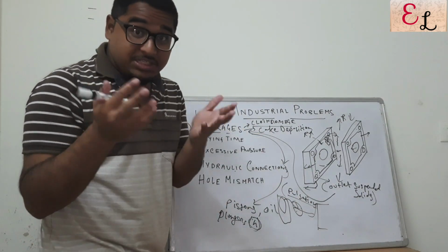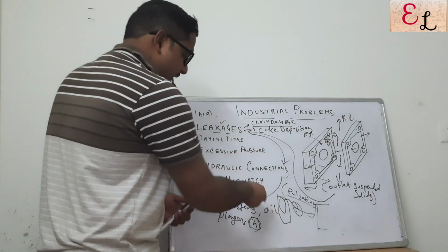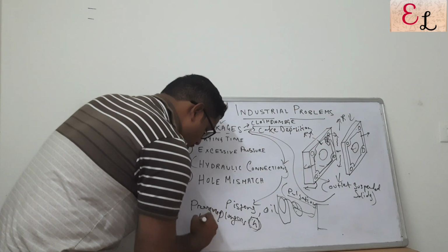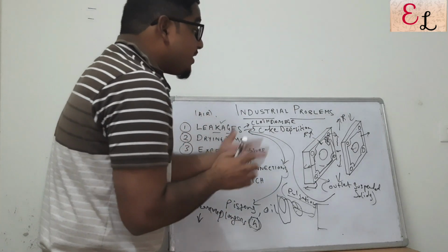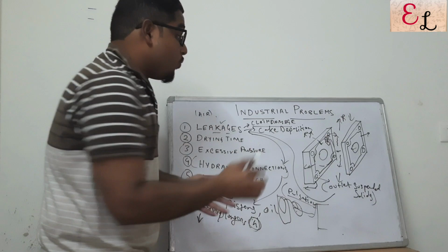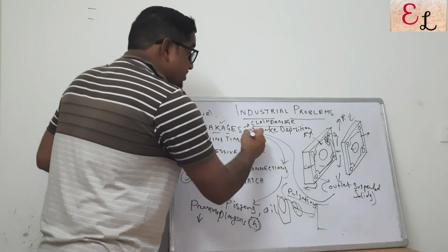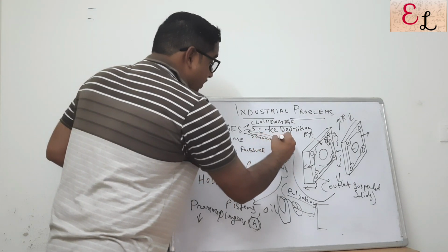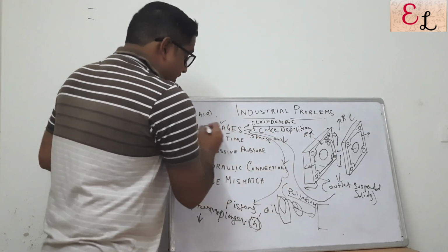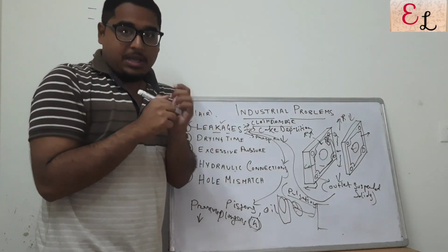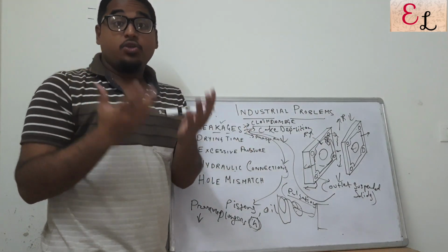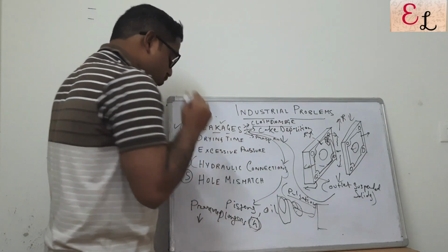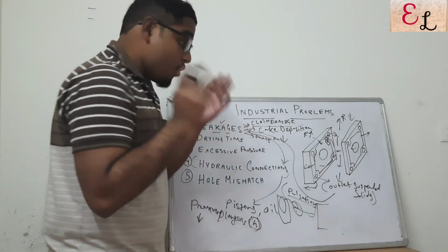Now, if the hydraulic connections are not proper, if the oil pressure, my friend, is not generated, if the pressure is low, very important, automatically the press will not close fully, and whenever there is a cake deposition, the leakages will start occurring. So if the oil pressure is low, then the filter press is more prone to leakages, and the leakages tend to occur regularly in the system. So hydraulic connections should be checked from time to time. So we are done with leakages, we are done with hydraulic systems and how to detect them.